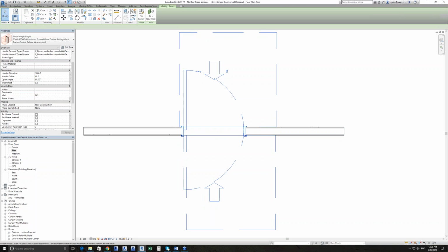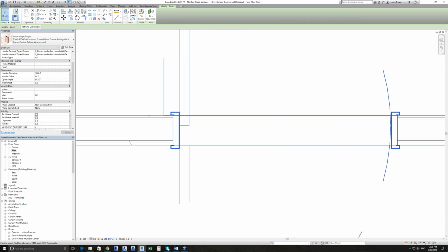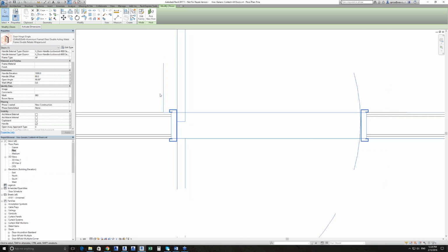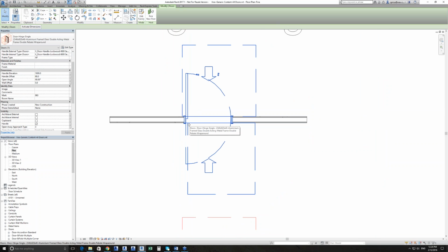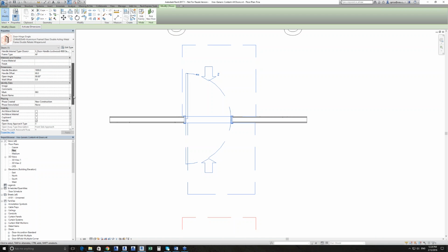And there are options within this wall. This one at the moment, you can see, is a wraparound type frame, so the actual type is called wraparound. There is a property in here where I can explicitly define the frame width instead of using the wall thickness. So I could make this a 150 frame explicitly. There are times we want to have it in a blockwork wall, for example, where it's not fully wrapping around a 200 blockwork wall.